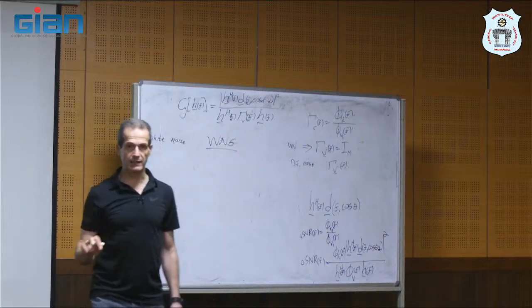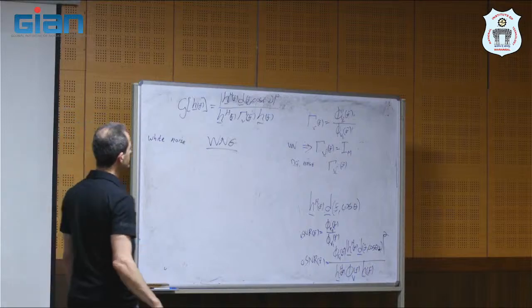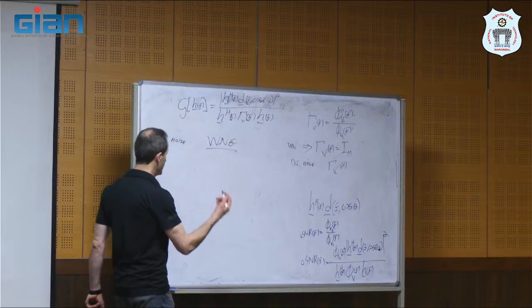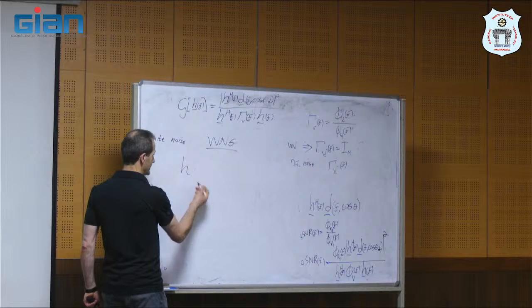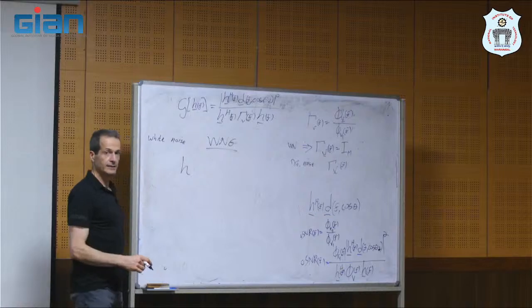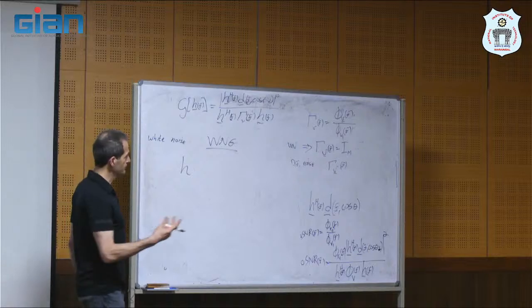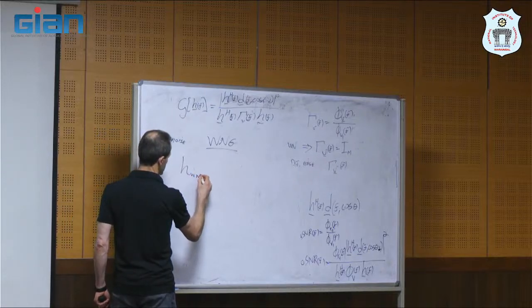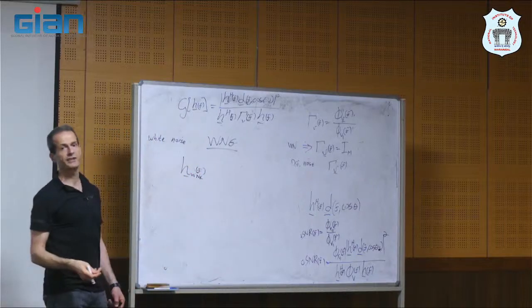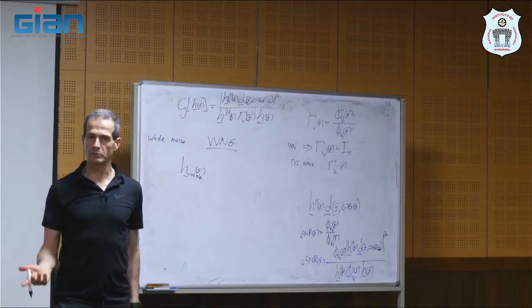The gain in SNR, when the noise is spatially white, the name for that is white noise gain. So a filter, a beamformer that maximizes the white noise gain is called white noise gain beamformer. Okay? It maximizes. It obtains the maximum SNR when the noise is spatially white.